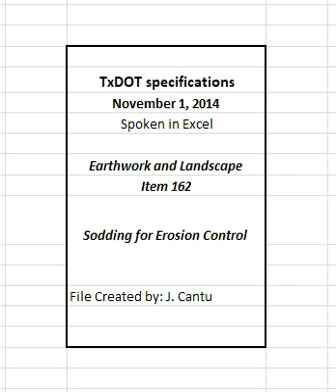4. Measurement. Spot sodding, block sodding, and straw or hay mulch will be measured by the square yard in its final position. Mulch sodding will be measured by the square yard in its final position or by the cubic yard in vehicles as delivered to the planting site.